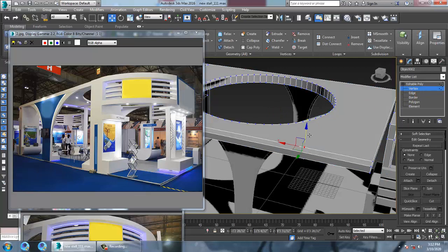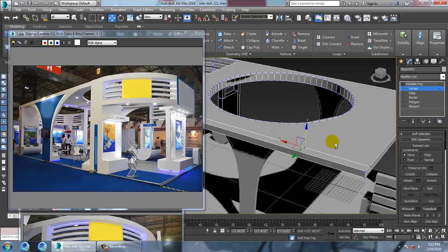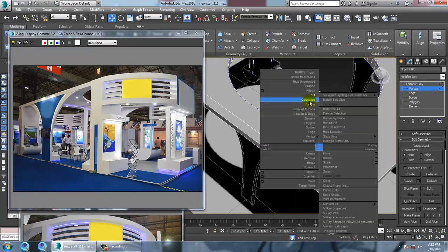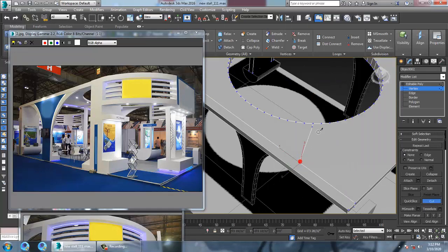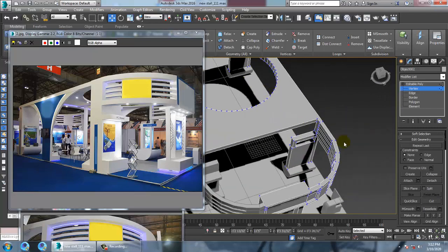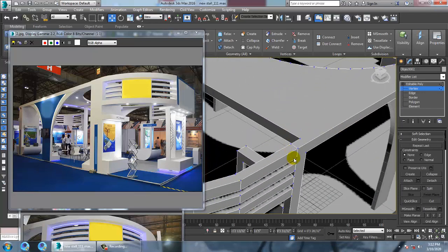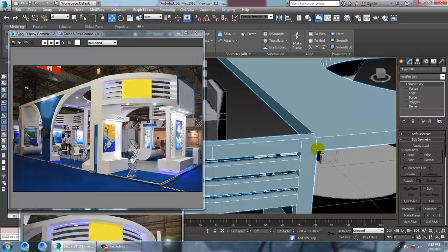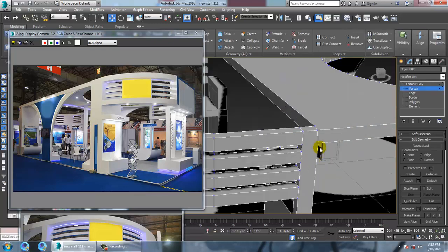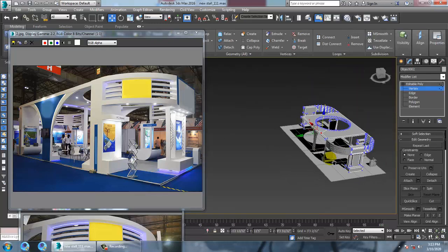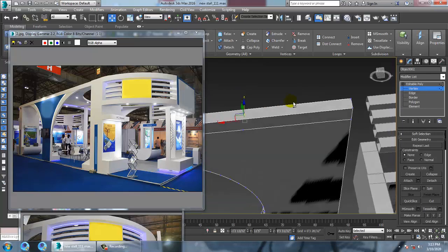this is just because of your ProBoolean, no issues. We will just connect this wherever it's going to create some problems. We'll just connect in this way, much better. So once you connect it, then no issue over here.